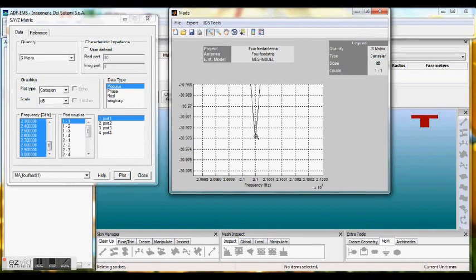So this basically represents how much power is reflected from the antenna. So for example, if S11 parameter would have been 0 dB, then all the power would have been reflected from the antenna and nothing is radiated. So in this case we have around minus 31 dB. So this means that the reflected signals are low when we operate in the following cutoff frequency.